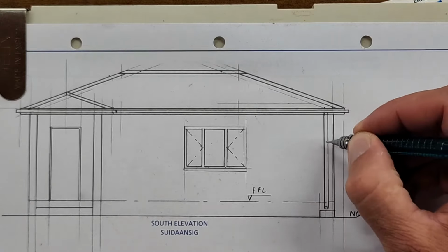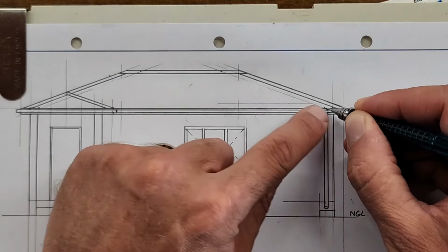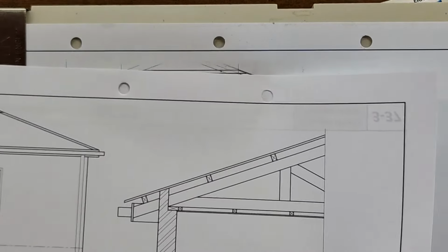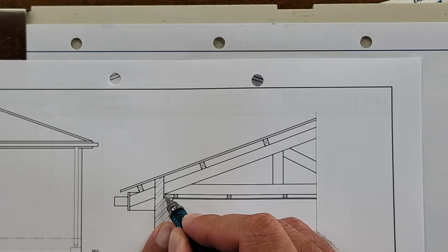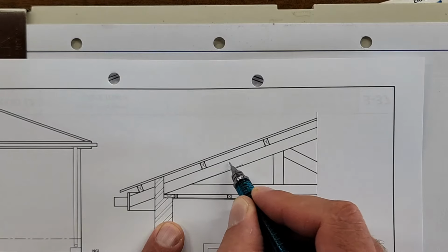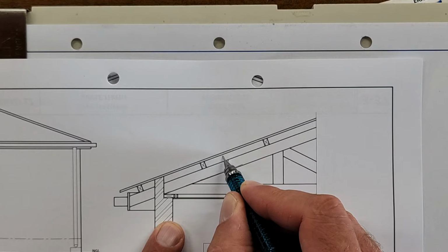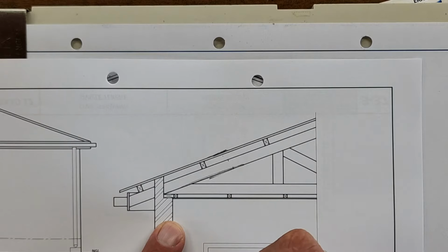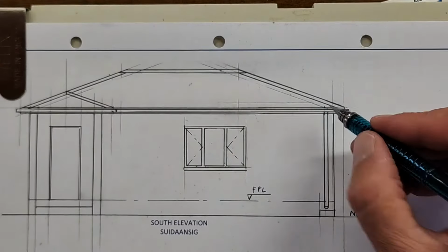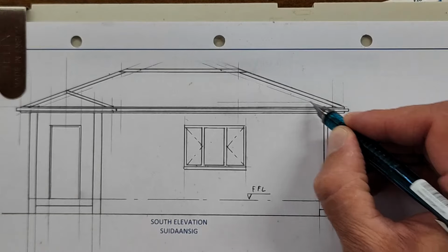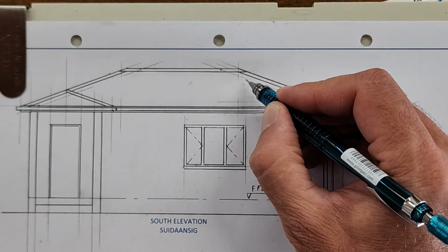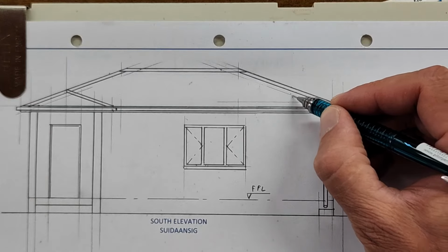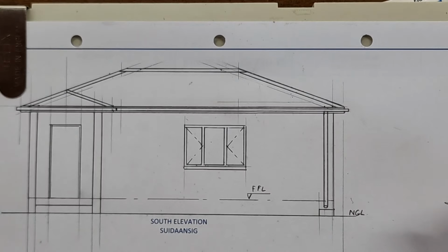We determined this point on the inner wall to get our 20 degrees, and then just like any roof truss, because look here, on a roof truss, what do we have to add? It was this point that I determined with this line, so I have to add that height plus the purlin height to get to that. I can't just make the top, okay? And it's this point that we determined here, and then did the first 20 degrees. Are you with me? Yes or no? And then we added the different components of that roof to get to the outside height.